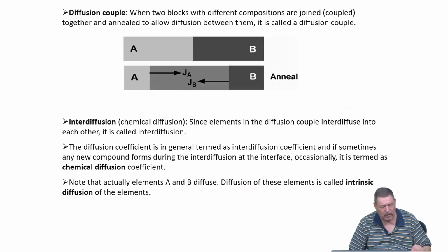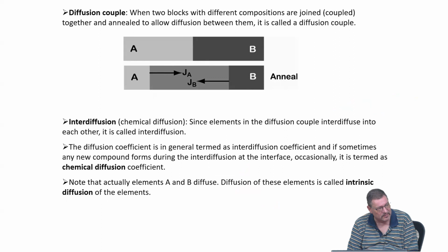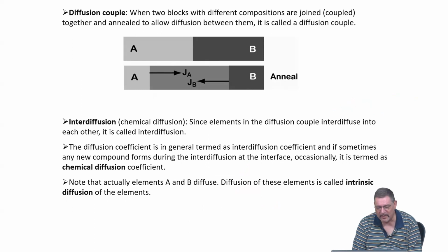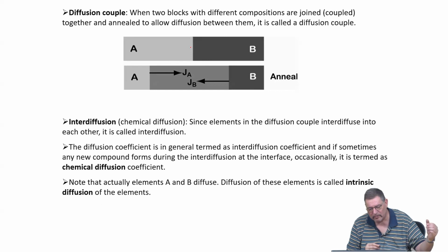So diffusion couples are important, also because the literature on diffusion in high entropy systems, the early ones on sluggish diffusion, were done exactly with this approach. And basically here it's sketched what is the main idea, right? So you bring together two dissimilar materials this time, and across the original interface, diffusion fluxes occur of some constituents from the A side to the B side and some constituents from the B to the A side.